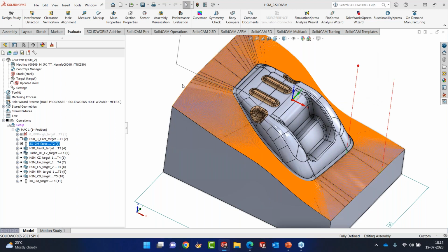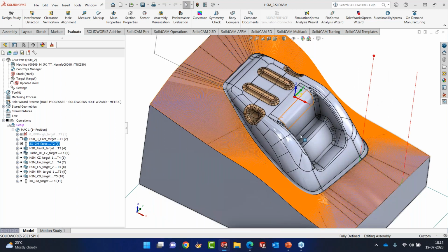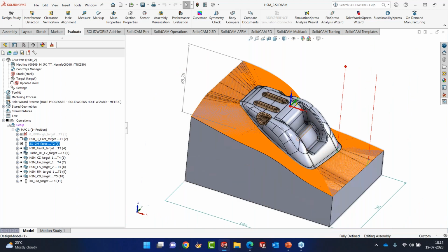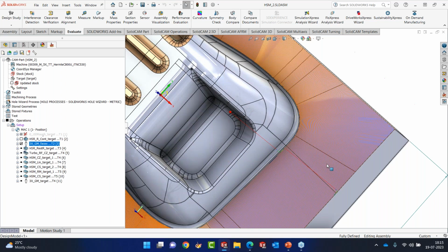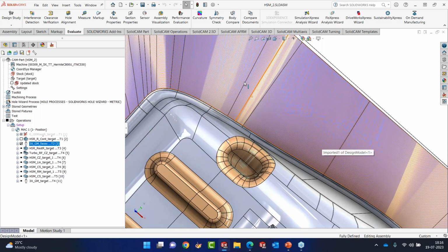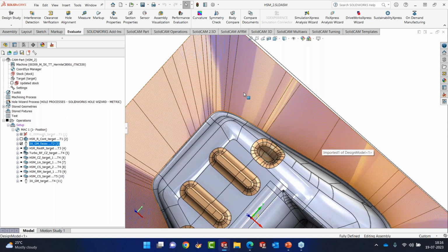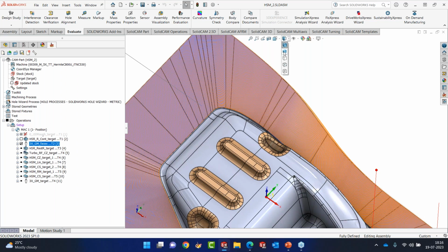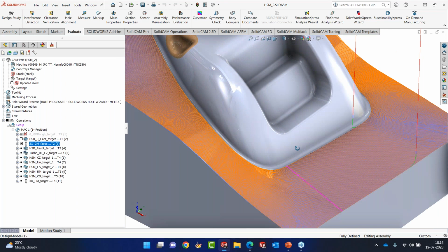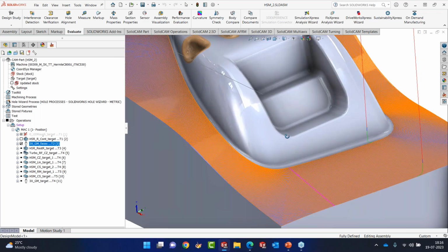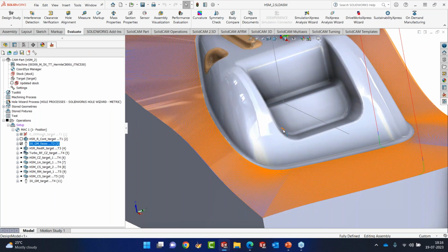That's done. And this is how the toolpath is going to look. There's one entry, one exit, and absolutely nowhere I'm seeing a step over. It's like a spiral that is being wound. Let me switch off that. Now you can see it's much easier to look at the toolpath. So it's a very, very clean toolpath that it generates when machining with Geodesic.